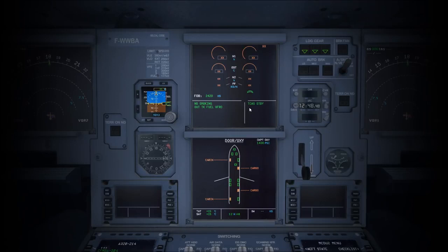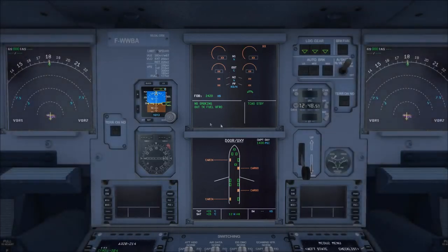So also in the center of the cockpit you've got several other instruments and buttons and various things. On the left hand side here you've got a standby flight display, so this gives you information about your speed on the left, altitude on the right, and you can change the barometric pressure setting by rotating that knob there. You can also enable an ILS landing system on that as well, so it's pretty much an all-in-one standby instrument. On the left hand side here you can see that we've got a terrain on nav display button.